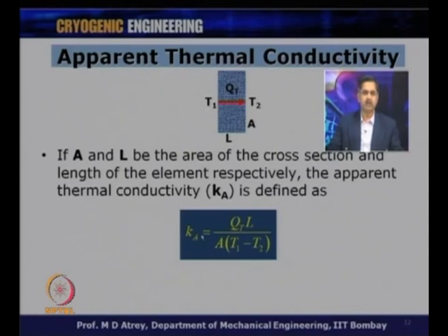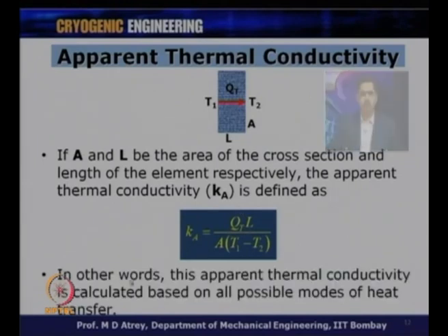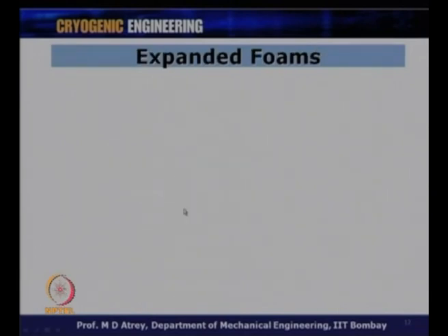And if I want to compare an insulation, I would compare it with the total heat transfer that happens because of all these three modes of heat transfer. So, in other words, the apparent thermal conductivity is calculated based on all possible modes of heat transfer. With this background, now let us come to expanded foams.